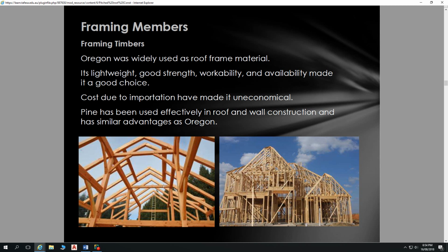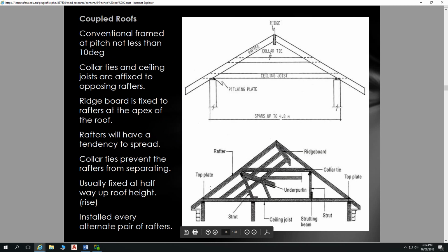So typically the new jarrah that you buy is a more pinkish colour, whereas some of the older jarrah that you can get from recycled timber places has that real darkness to it. It's a very hard and durable wood. But certain species of termites also love to eat it when it's wet. Termites don't want to touch it if it's kept dry, but put it in the ground and it's maintained, and termites really enjoy it.